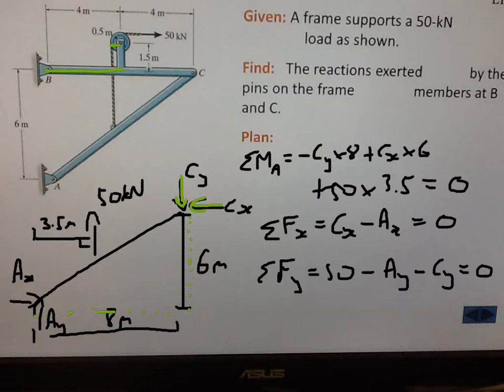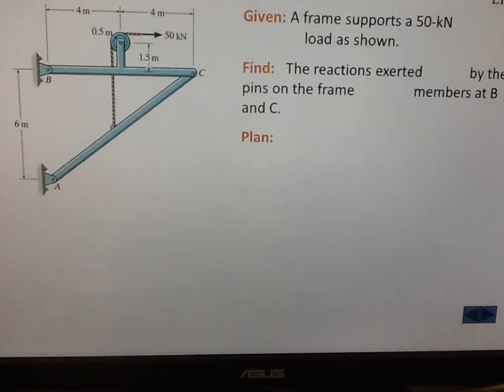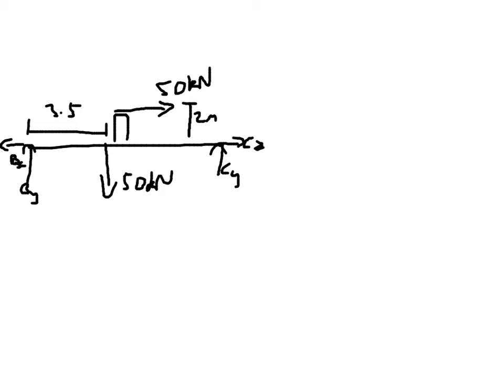So now what we'll do is jump onto the new slide, and we'll look at the other piece, BC. Again, I'll draw it and I'll come back live. Okay, so here's our free body diagram for the second part, BC. I've got a 2 metre measure there. It's 1.5 metres to the middle of this pulley, which I haven't drawn on, and then another 0.5 metre from the middle to the outer radius. So to the rope with the force, it's 2 metres total.